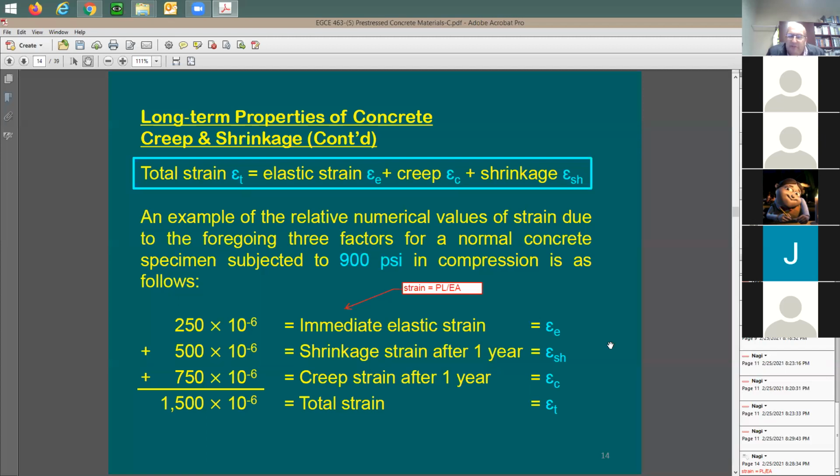Yeah, generally speaking, there are certain additives that you add to the mortar to gain high strength in a short time. Because usually with masons, as you know, you put up the block wall and you'd like to grout, maybe the next day if you can, right? The problem is the stability of the wall itself. And of course, you don't want to shore the wall. You don't want to brace it because it's going to be an additional cost.